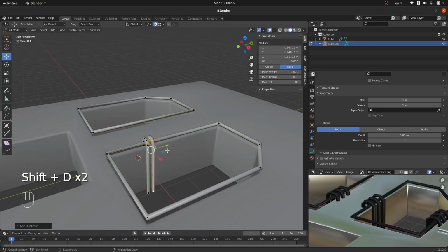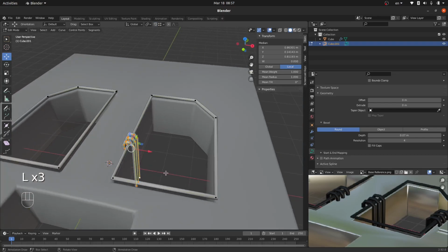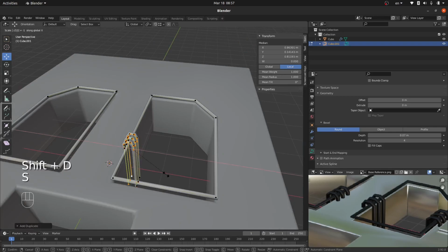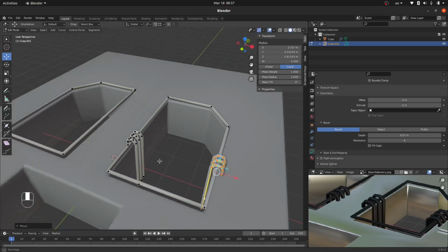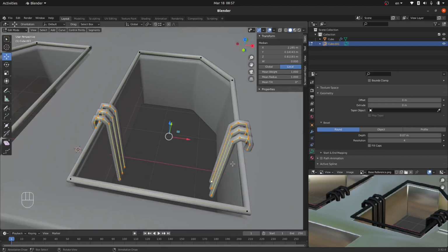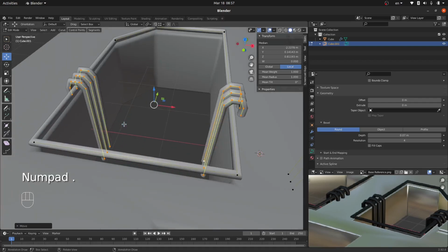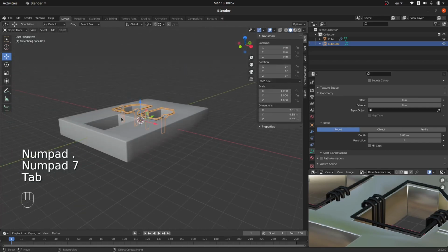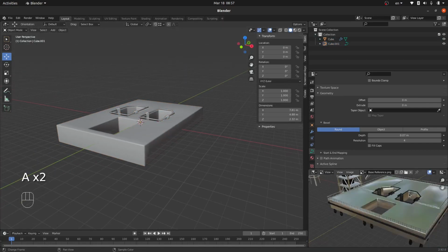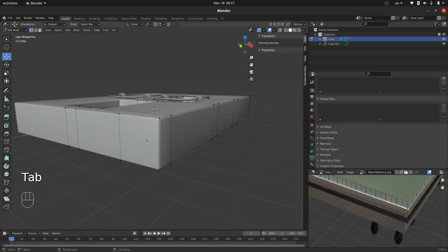So this is the first time, Shift D again, and yeah, I'm going to just deactivate the snap tool, and L to select the other units, Shift D, S X -1, and let's move it to the right side, just like that. Okay, and after that I'm going to be selecting all these units. So I highly encourage you to add more details to our base, because it's going to add more realism. So the more details you add, the better results you're going to achieve. Alright, so we got it right at that spot. Okay, so also we got another type of pipes on the side. You can see those.